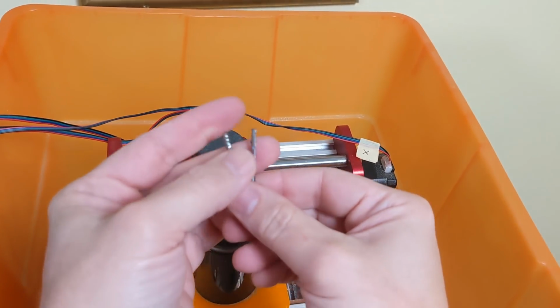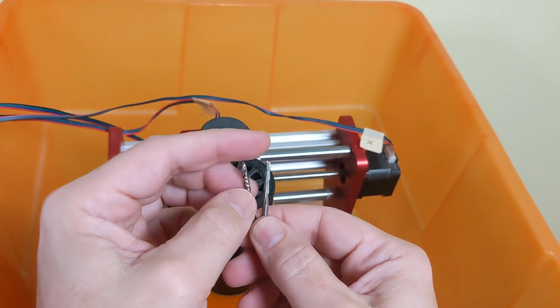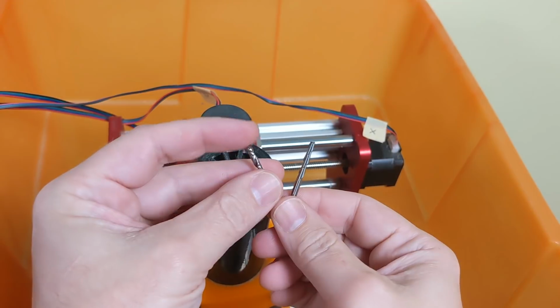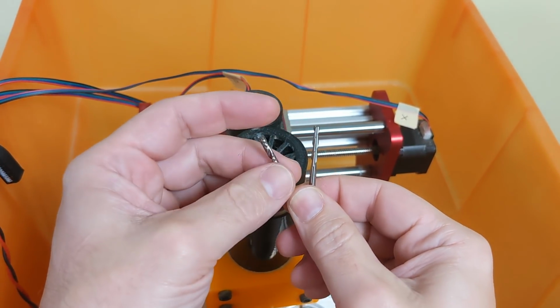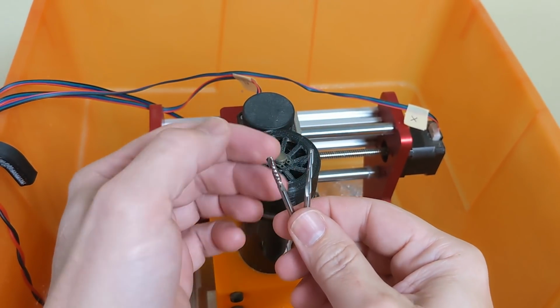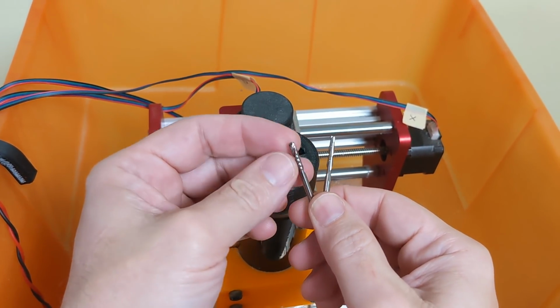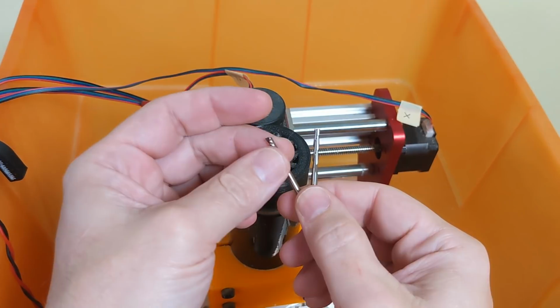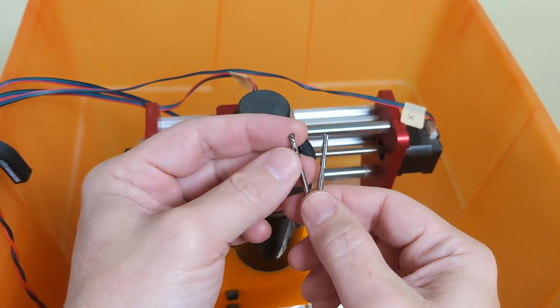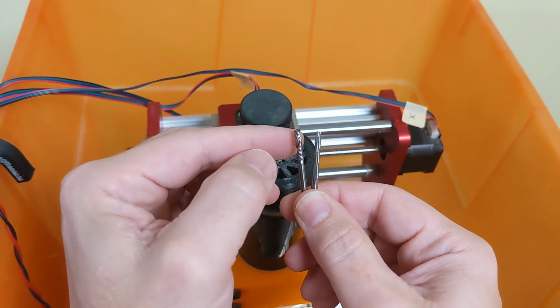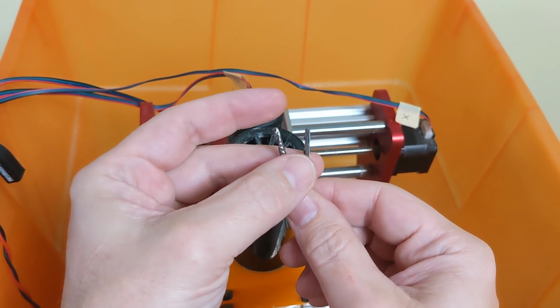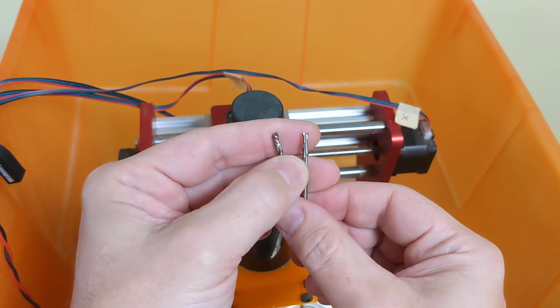Let's have a quick discussion about flute count and RPMs. So this is a single fluted end mill. This is a double fluted end mill. Of course, they go 3, 4, even 5 flutes, although 4 is the highest that I've ever actually used. So the lower the flute number, the better it is at clearing chips, but the worse it is at being strong.